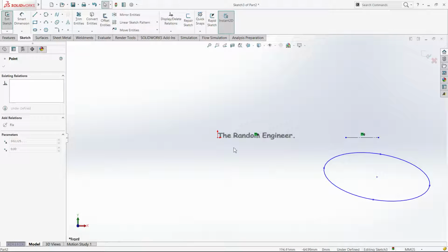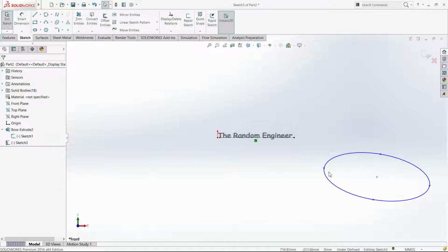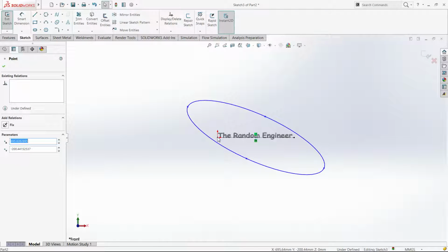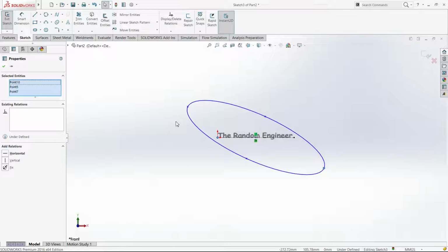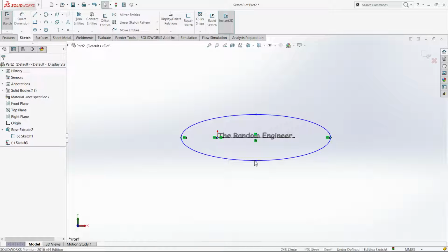So I'm just gonna drag this point onto the origin. It's gonna tell me coincident relationship, and same with the other line. It's gonna be a coincident, and I'm gonna drag the midpoint of the helix and drag into the midpoint of the line, and it's gonna tell me it's the middle point by the look of that yellow relationship. And I'm gonna do the same as we did last time. We're gonna select those points and make them horizontal. I'm gonna select these points